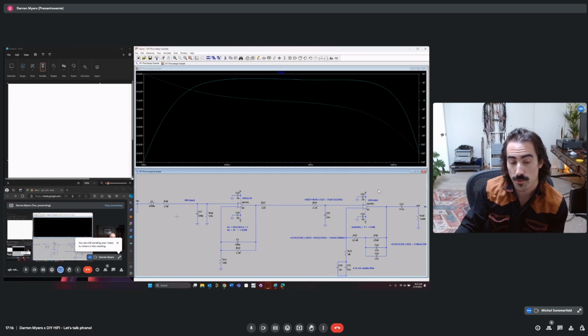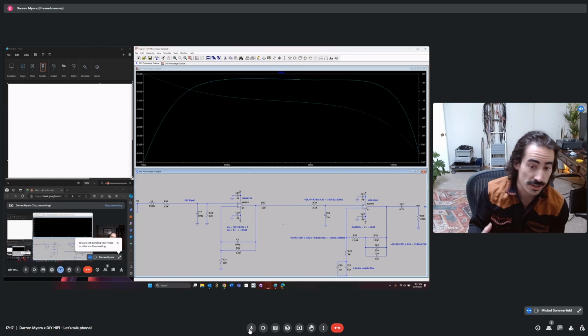And so for amplifiers that have to amplify a signal coming from higher source impedance, JFET amplifiers are actually preferable and have better performance when amplifying a signal coming from higher source impedances. And this is particularly because JFETs have a really low current noise spec. And so the current noise is actually what you're worried about when you're talking about an input.